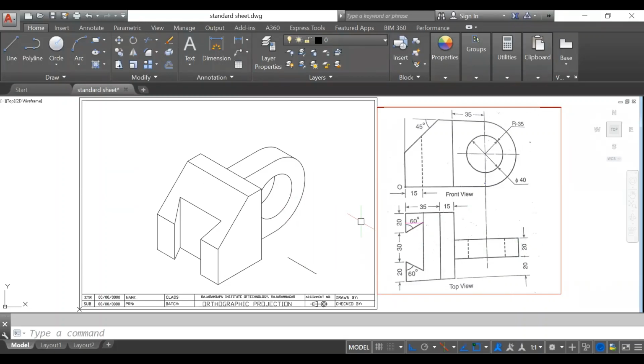So here, what is important, that angles will not work in the isometric. You have to use the trigonometric rules and you have to find out the distances. And according to distances, you have to put the dimension on the isometric drawing. Okay. So that is very important here.